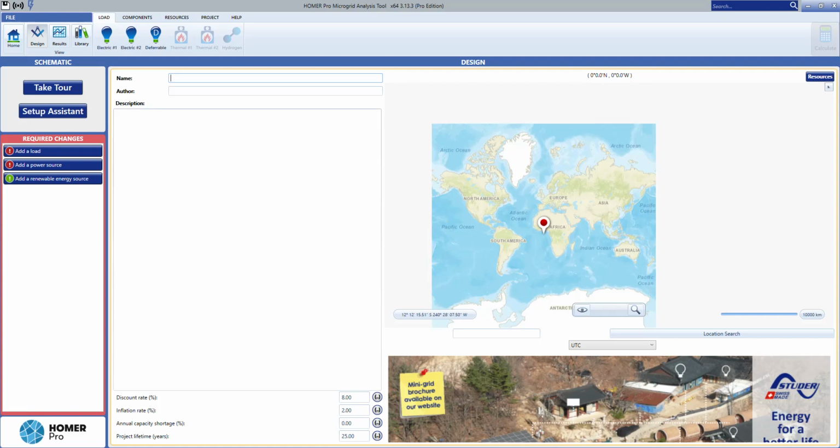So it means that you say, okay, I want to have a renewable energy system with only, for example, photovoltaic modules, and I am allowed to have 10 percent of shortage during the whole year, which is a really high number, but just as an example. Usually you say, okay, I don't want any capacity shortage, so this number should stay at 0%.